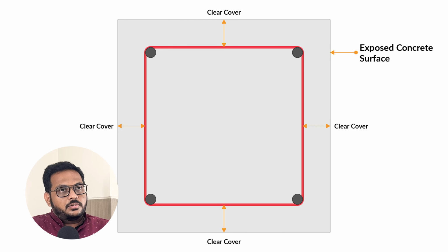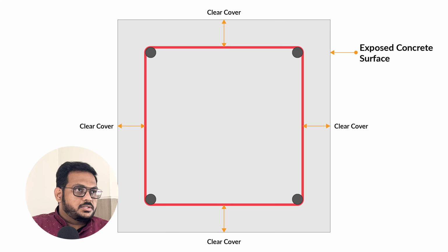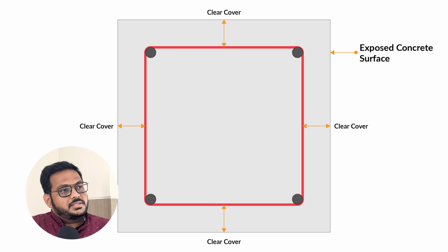Heating is like we have a rating: we expose the element for 120 minutes, and on that basis we decided the cover of that element. That cover is the distance between the outer face of the element and the reinforcement. For this project the exposure condition was 120 minutes, about 2 hours, and on that rating we decided to take 50 to 75 cover for each and every element.